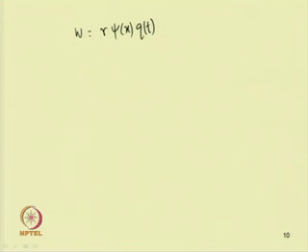In this case one can take only a single mode, but instead of taking a single mode, one can consider multi-mode analysis. So, here one can take R I into psi I x and q I t, where psi I x is the shape function of the ith mode. Already we are familiar with the continuous system, the linear continuous system, in which we know that it has an infinite number of modes.